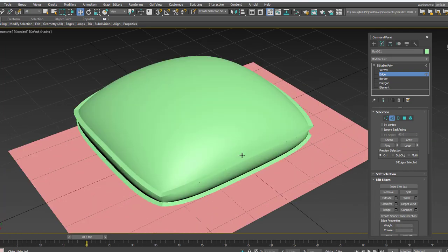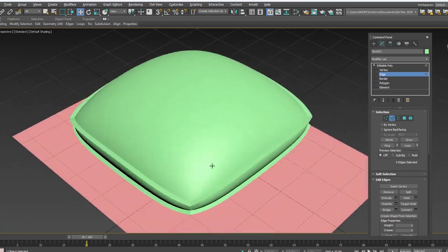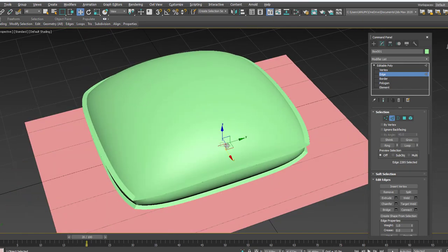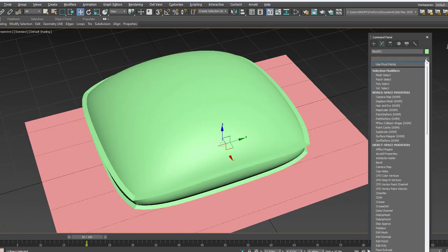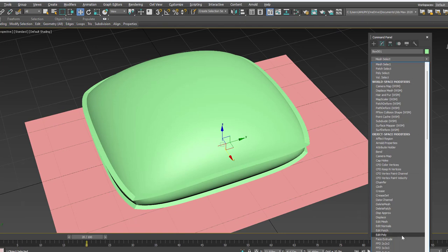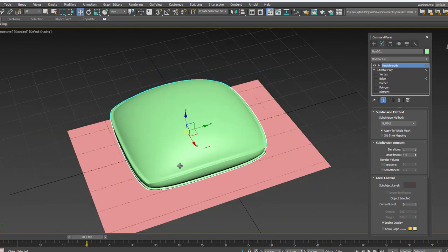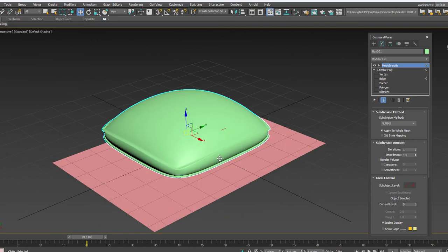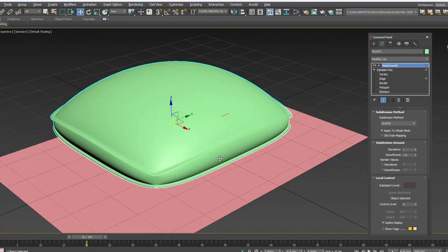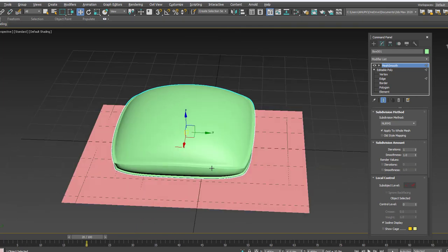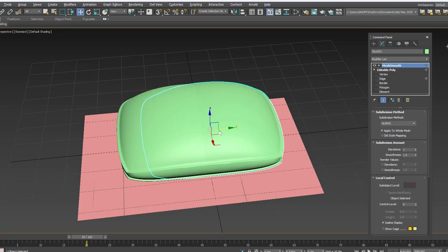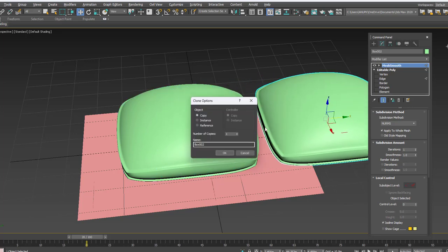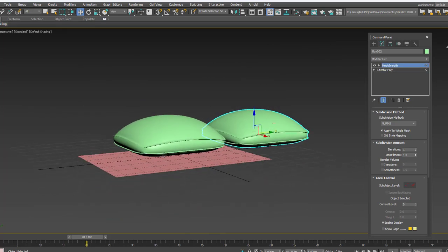And then F4 off. And then even if you want to apply the smooth, then you can go to the modifier and then apply the mesh smooth modifier, a little. And then in future if you want to apply the material, then you can apply the material to this pillow and you just copy it multiple times. You can go with any other shape.